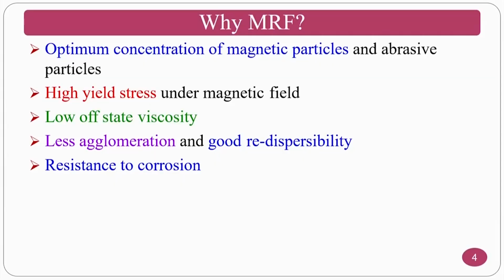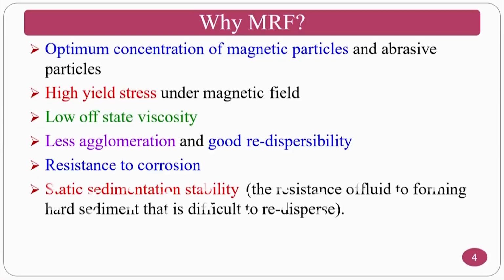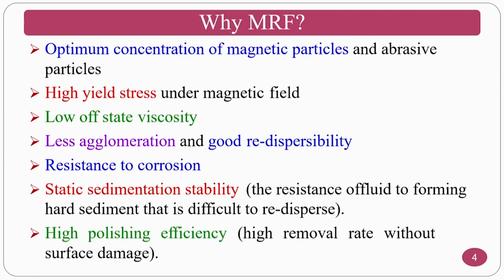Okay. Resistance to corrosion, because you don't have any water-based fluid. There are magnetic fluids which are water-based, but most of the magneto-rheological fluids will not have water content. The static sedimentation stability, that is nothing but the resistance to forming hard sediment that is difficult to disperse, and high polishing efficiency. Normally this particular process will have good polishing efficiency because of high material removal rate without any surface damage on the workpiece.